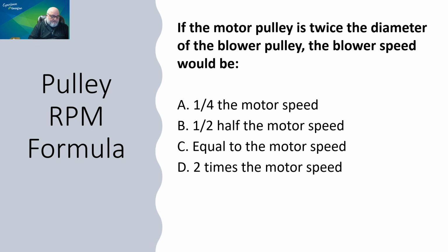So increasing the motor pulley to twice its original size will increase the blower speed twice. That makes D as in David the correct answer.